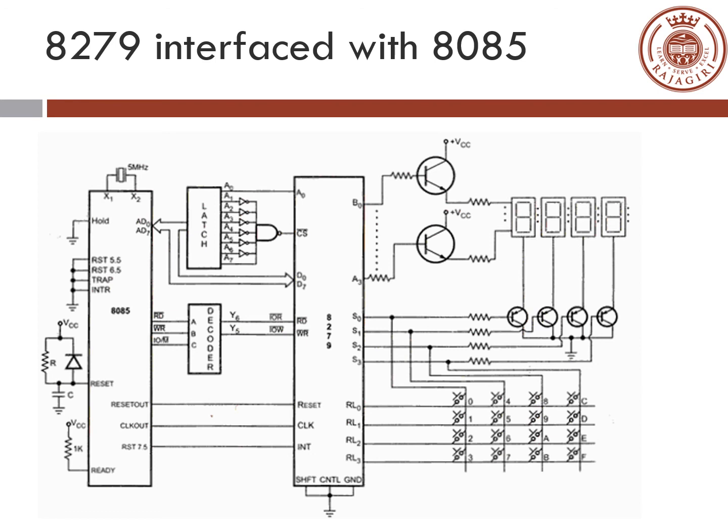So we already talked about how the chip select is connected, and this shows how the address lines are coming from the 8085 to the NOR gate, and the A0 is connected without inversion to form the chip select and the buffer select. Then it also shows the read and write bar enables, which are generated from the read bar, write bar, and IO bar M signal from the 8085 through a decoder to generate these two signals.